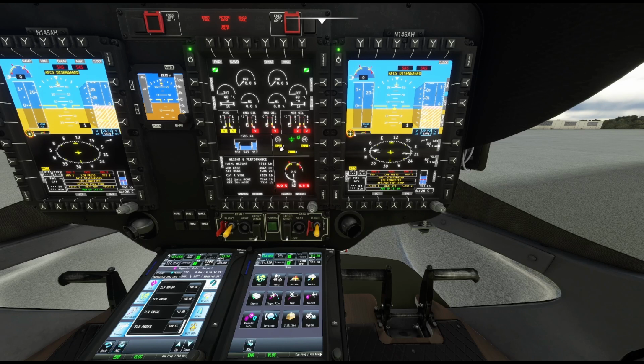All right, this right here actually should not be showing because I have not hit the number, so this is not an over limit right now. The only time that you will see these numbers in the current state is if they're outside of their normal limits, and they'll be highlighted in a color. So these are highlighted in yellow, saying that it is under voltage, but this would not show like that because the aircraft knows, obviously, it's under voltage. It's not even online. The battery voltage is obviously within limits, so it's not showing that voltage.